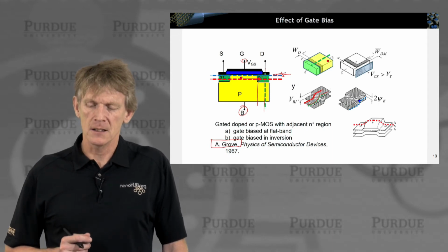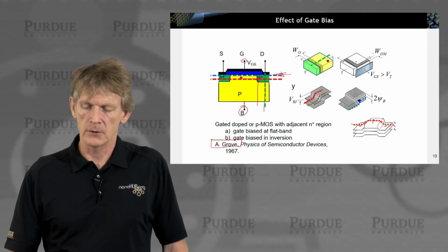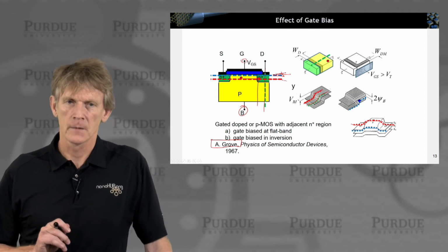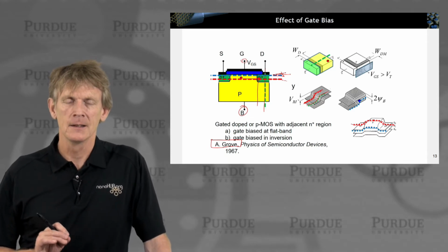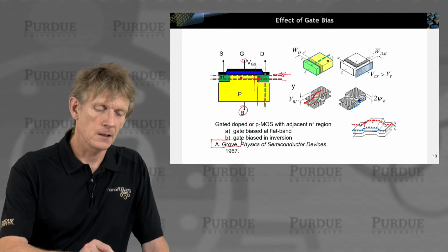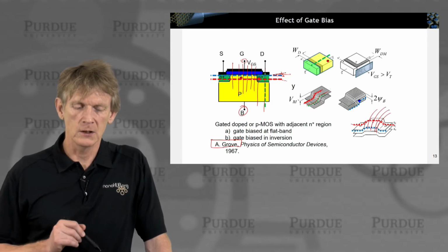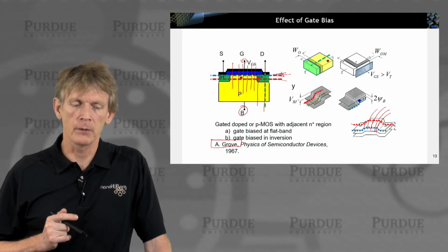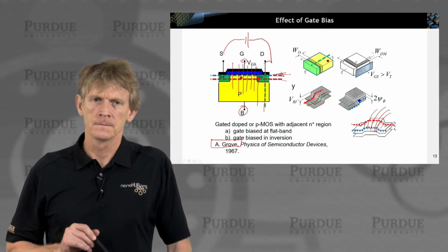All right. So in this sketch here, I just took the red dash curves from here and laid them over here deeper away from the gate. And closer to the gate we have the blue curves, okay? So depending on where you are or where the electron is, it sees a different potential, and us as trying to figure out what is the charge distribution along the channel here, we need to know this along the channel here, the sketches I just made. We need to resolve that in this direction, and it can be complicated as we apply now an additional voltage between source and drain, okay? So, important.